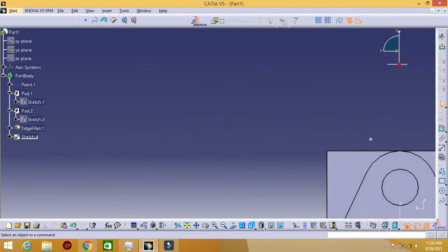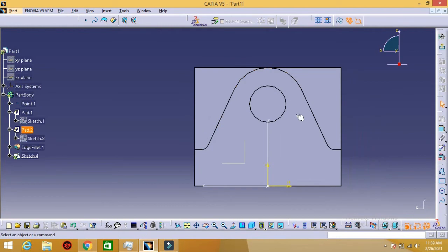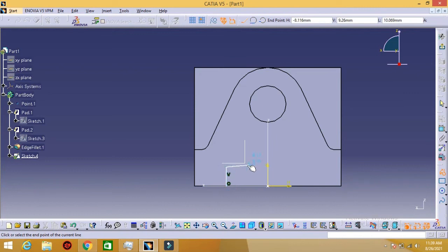Now it is a little bit to the side. Let me pan it and go to the middle. Now I will draw my sketch here. Removing the sketch, let me click profile, let me make a similar sketch. Horizontal lines you just make. See, when I am taking it up, now it is blue because it is completely vertical.